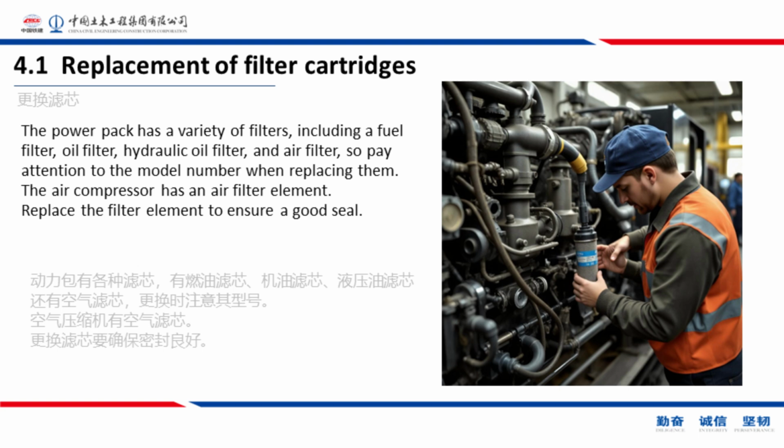PPT 37. 4.1 Replacement of filter cartridges. The power pack has a variety of filters, including a fuel filter, oil filter, hydraulic oil filter, and air filter, so pay attention to the model number when replacing them. The air compressor has an air filter element. Replace the filter element to ensure a good seal.